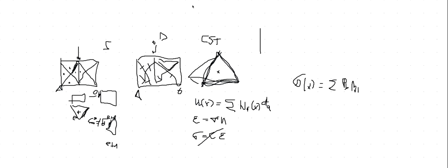This is a function of X. So what you want to have, if you have this type of constant strain triangle, typically you take these b's to be the middle of each edge. And then these betas are typical of these values here. And we want to make sure that if you have this unit vector of exterior normal n, that when you compute your stress vector, Tn, by Cauchy principle, being equal to sigma times n,